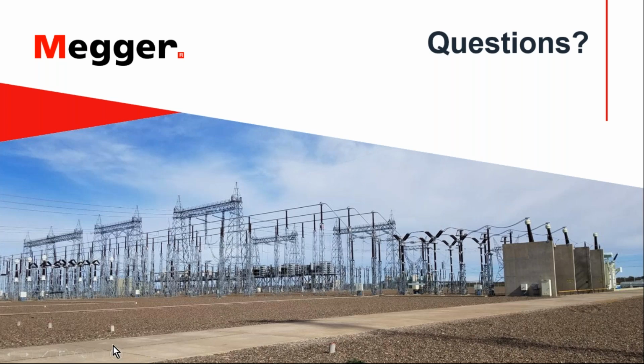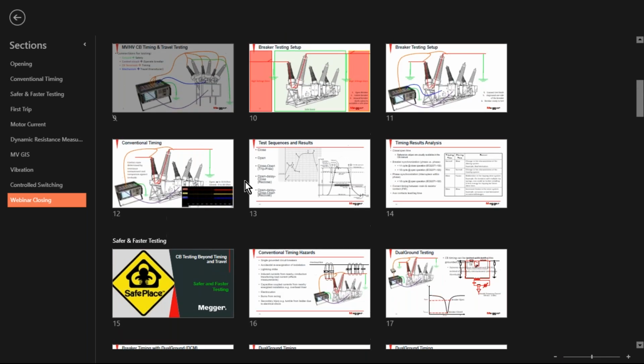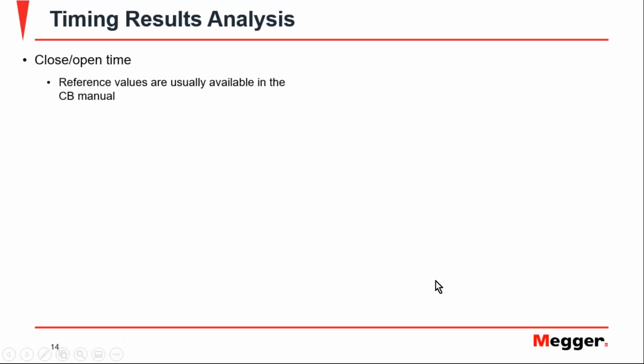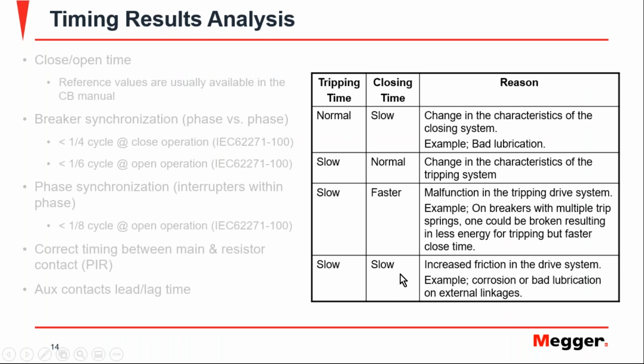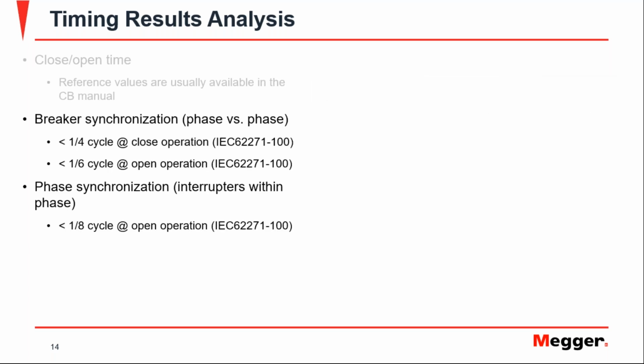It is still valuable to measure if you don't have any previous data, because you will probably be able to find guidance from the manufacturer on what is specified for this breaker and a timing interval, and you can always compare to that.